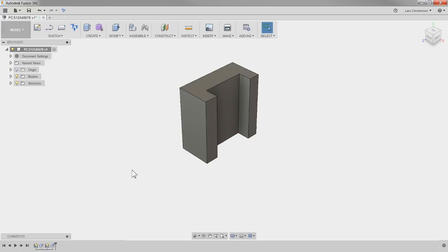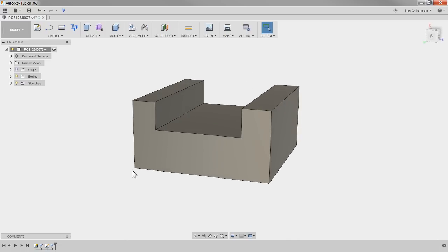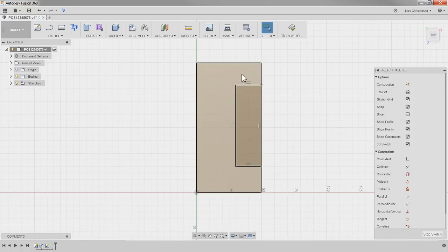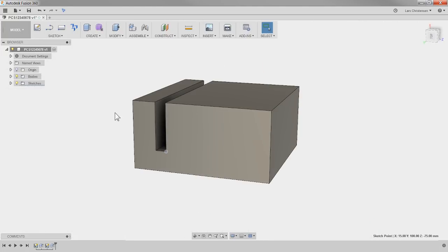Now, this is my biggest mistake. I call this my $500 mistake, because that was actually what this ended up costing me when I started out with CAD. You need to fully define your sketches. So if I go back to that sketch I just created, that rectangle, right? You see how it's blue, it's not black. Check this out. If by mistake you grab a corner and drag it, what are you doing? Well, you are completely changing that shape.